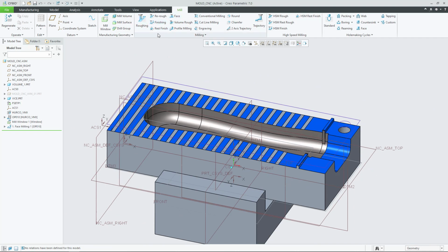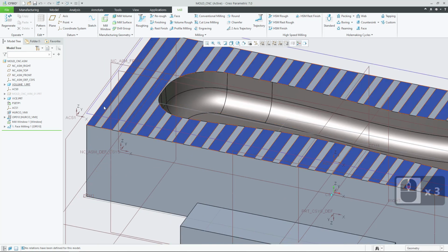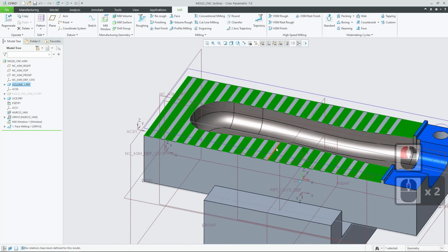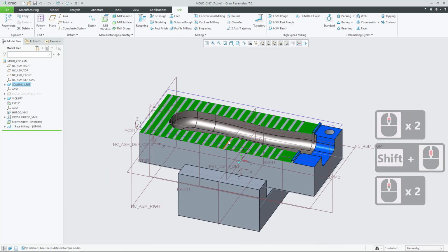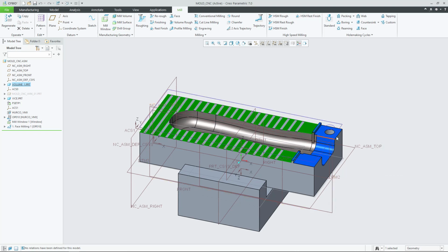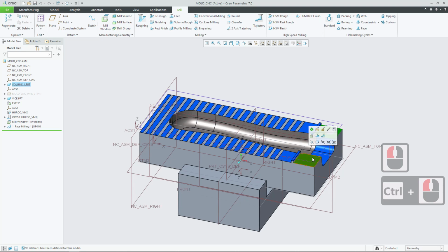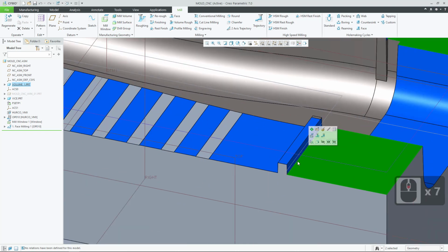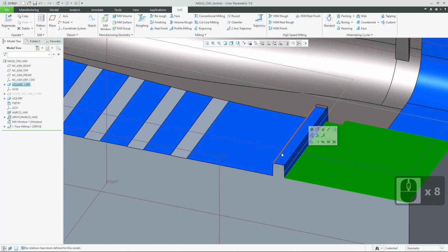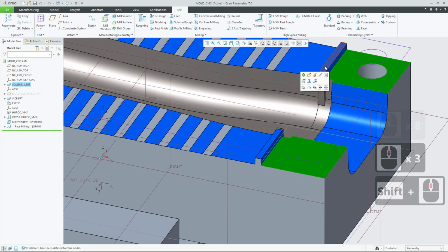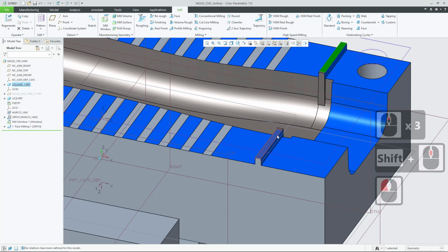I'm going to use a roughing operation, but I'd like to direct the tool to this surface here. So this blue surface that I've just selected, now highlighted in green, I'd like to machine all the way down onto that surface, both here and over at this side as well. I'd like to take the level of the top of the block down to that level, and then obviously I want to leave these two island areas that stick up alone.